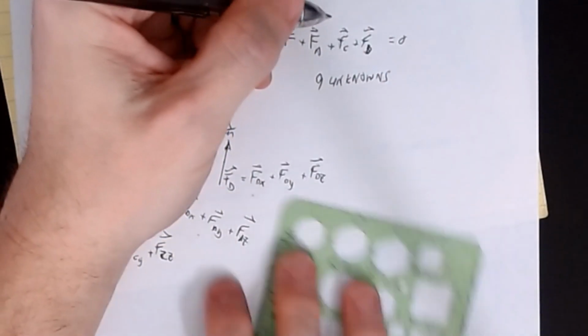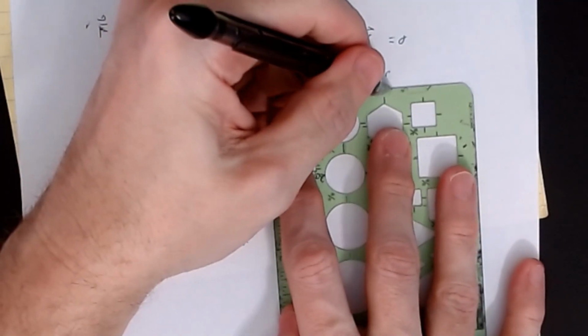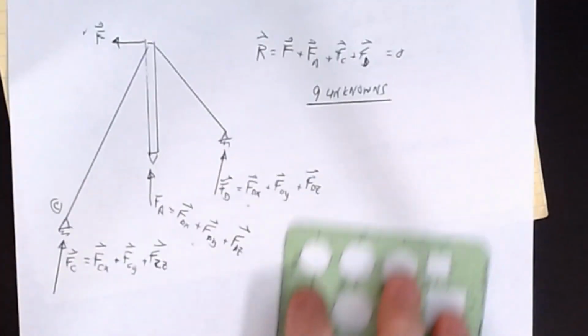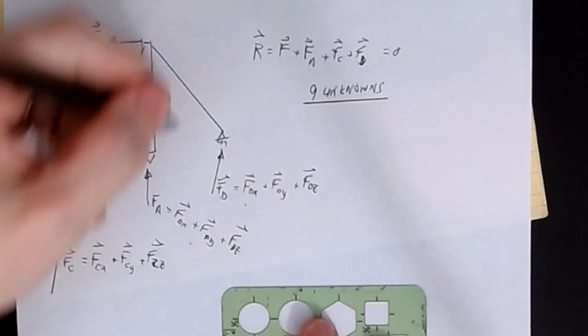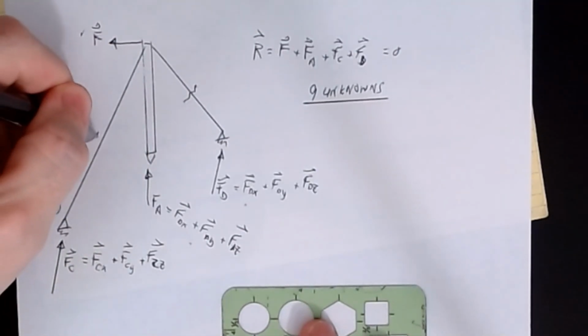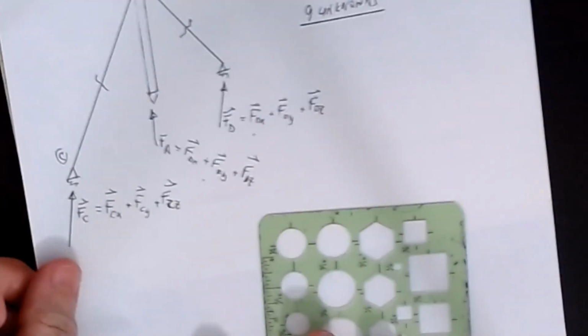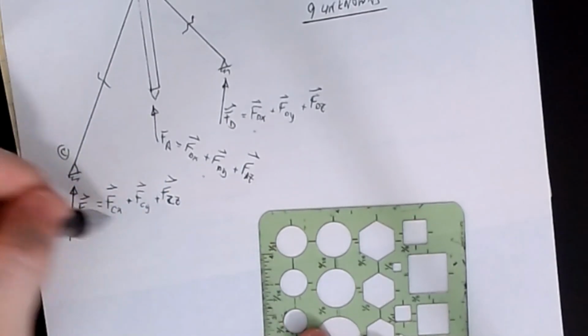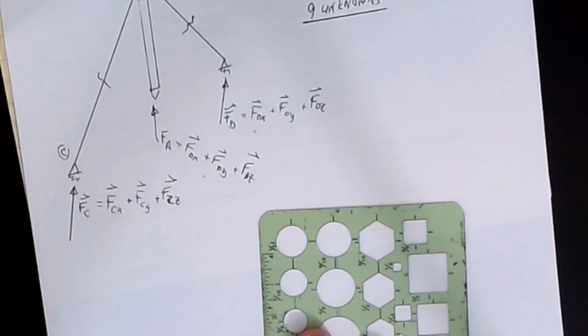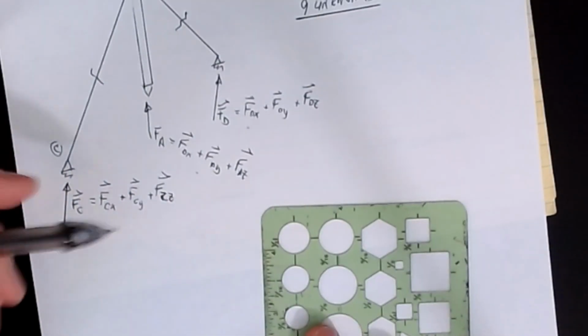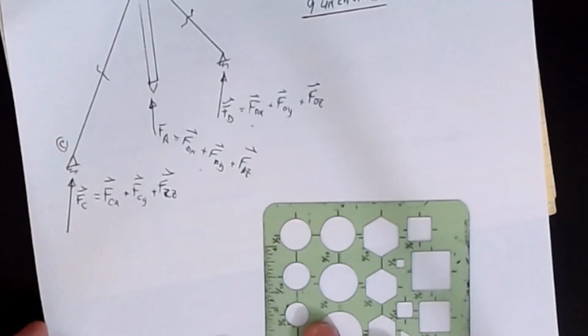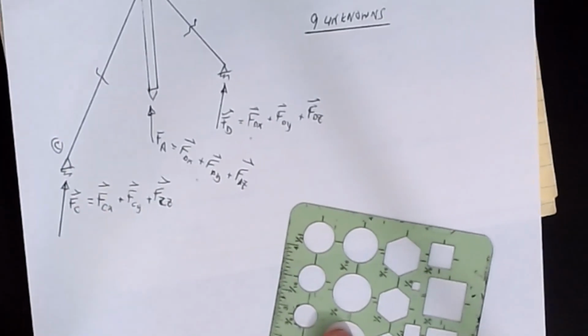All right, so one of the tricks that comes out of this, and one of the reasons I want to show this problem, is that anytime you have a cable, it's often better to cut the cable, and here's why. Okay, so keep that in mind. If I don't cut the cable, I get 3 unknown force vectors down at the reaction where it's tied to. And you could work through it eventually, probably. Actually, I think it's statically determinate if you don't cut the cable, but yeah, it's not a real enjoyable time, not how I would want to spend my weekend, needless to say.